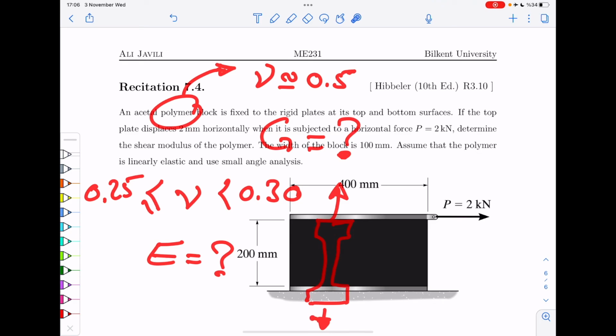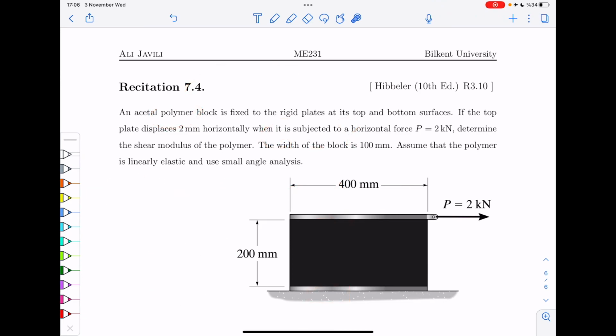For some materials, E is the bigger question. For something like polymer, G is usually the question, and this is exactly the way you are going to test this. Sometimes there are things called rheometers, where they take a disc and apply a shear via torsion to it. We also come to that. But anyway, the question is like this. My point being that you should pay attention to the direction of the force. What happens to this sample is that it becomes like this after you apply that force.